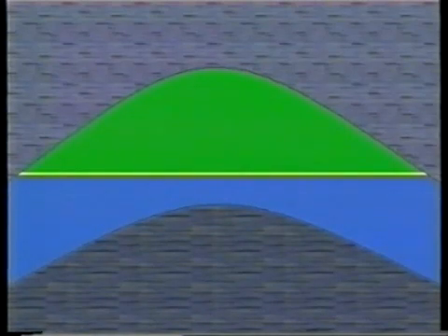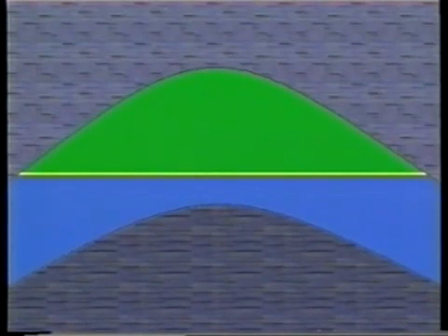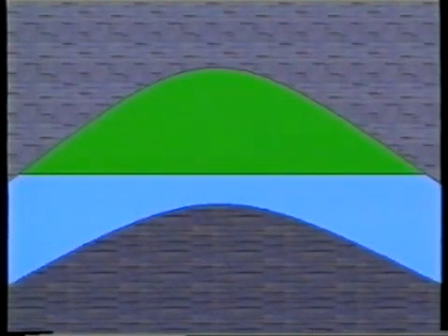This reservoir shows an oil-water contact. In a formation where the clay content is negligible, we might expect to see a low water saturation within the oil portion of a reservoir, while below the oil-water contact, water saturation would approach 100%. It is essential to note, however, that the water saturation percentage determined at any point in a reservoir will not necessarily be the percentage of water recovered with hydrocarbon production. This is a critical factor in wireline log and reservoir evaluation. Let's look into it further.